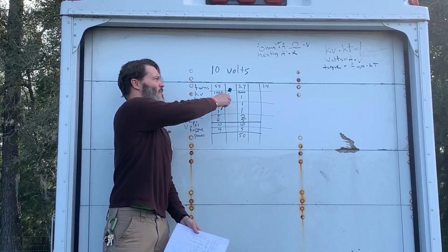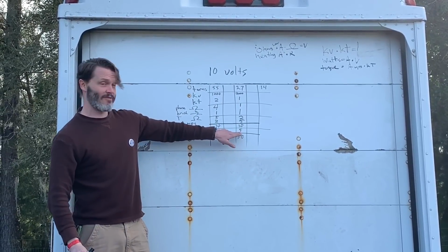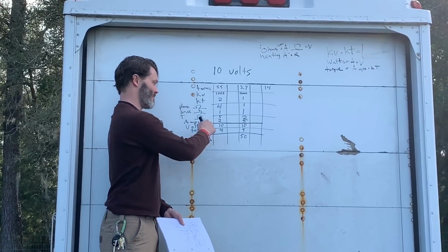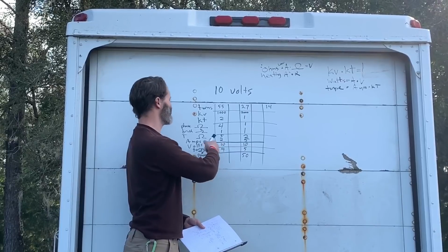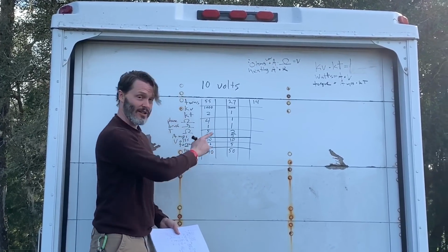As you can see, when we went from a 27 turn to a 55 turn motor, our torque actually dropped from 5 units down to 4 units. But we're only pulling 40 watts to get it. Power is our volts times our amps, so we're at 40. All right, so now let's go in the other direction.